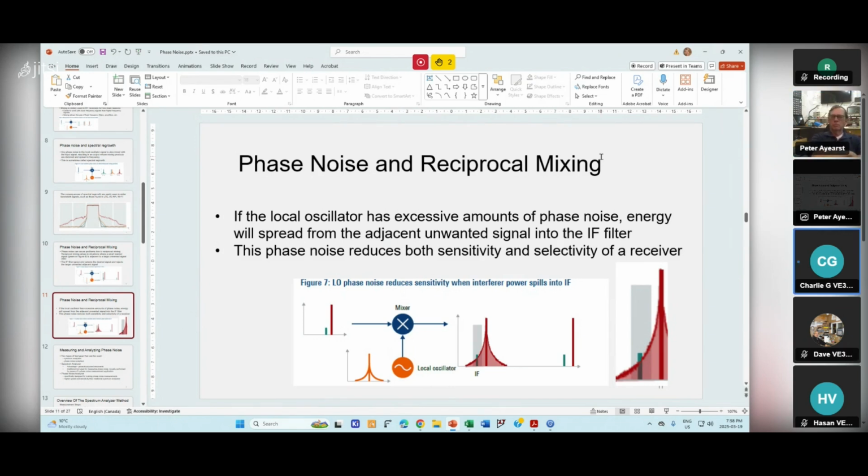So Dave, you're coming at it kind of backwards, right? You really do this from the design spec when you're starting to build the thing. What's the sensitivity you want of the receiver? How much phase noise can you tolerate? Then design your circuit to produce less than that amount. Measure whether you're producing less than that amount or not, and you're done. If it deteriorates over time, if you find less sensitivity, you're starting to lose signals in the background noise, then maybe run it through and test again and see if maybe the root cause of that is phase noise.